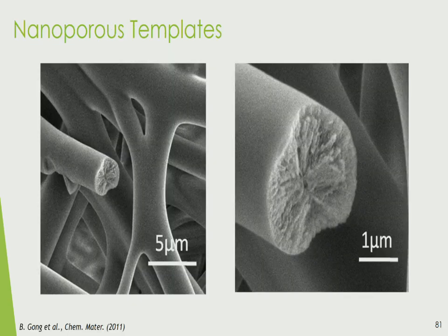So this is on PBT, so it's polyester. Remember, that polyester is open enough, the pore volume is open enough, that I can diffuse all of my precursor in, and it completely modifies the material. So we take a PBT polyester polymer, and we do our process, and then we burn it out and anneal it at a high temperature. We can get rid of all of the organic component and just leave our mesoporous oxide structure. And this is what it looks like. This confirms that it's diffusing all the way in and reacting with the entire material.